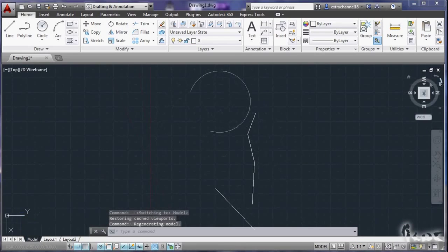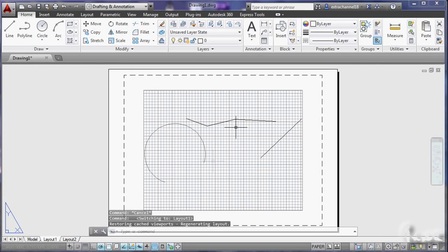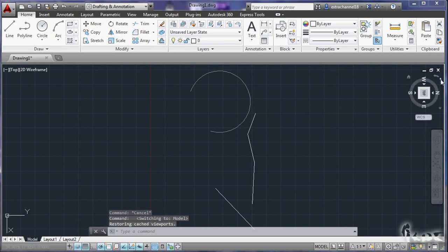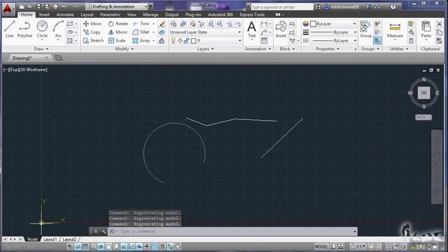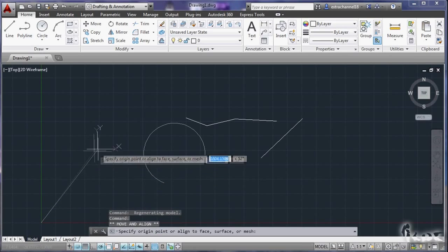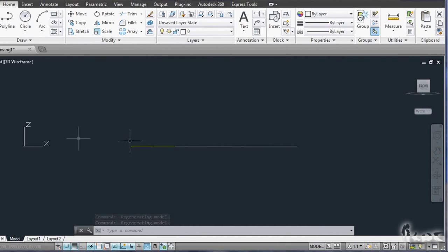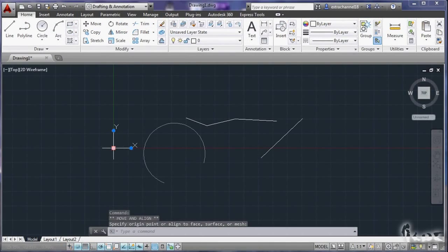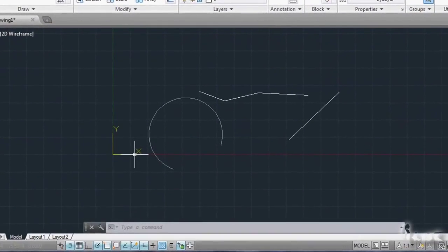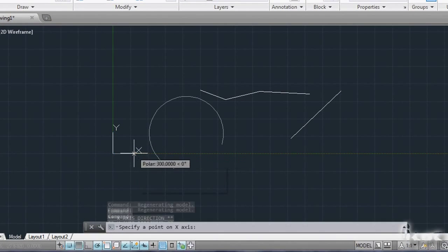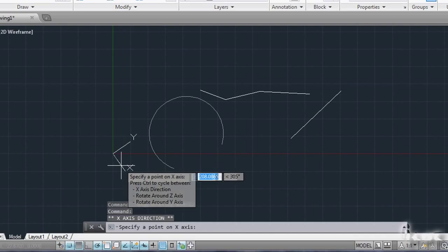Rotating the workspace using the 3D map won't rotate the drawings in the final layout, since they are used just to change the point of view. If you need to rotate the Cartesian axis, they are like objects in your workspace that you can pick and move. This will locate the X and the Y axis, and so the direction and the positions. There is also the Z axis, but this is for 3D models that I will show in another tutorial. The blue square will move the system, whereas the rounded ones will rotate the graph, but not the drawings inside.